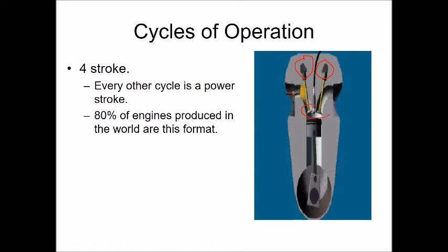These are the cams which actually act on the valve. So we've got the valves in here. The inlet is on this side, and the outlet valve, the exhaust, is on this side over here. So here's the piston, and the combustion takes place in this volume in here. So this is where the air is going in and out of.